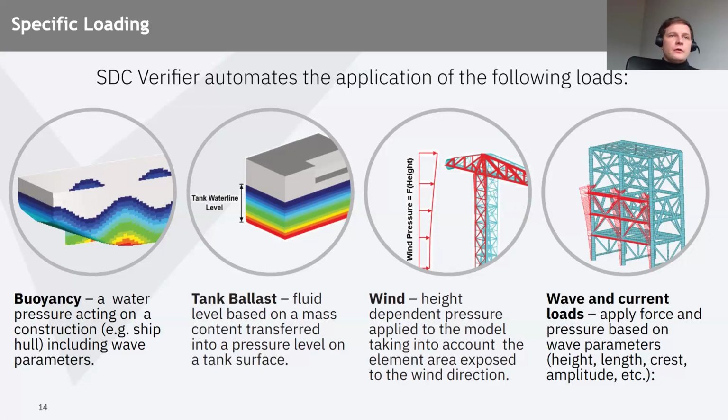buoyancy load of water pressure of the floating constructions, or tank loads, or distributed pressure of winds, waves, and so on. So the complex loads are, of course, automated within certain tools within SDC Verifier, and application of the simple loads like nodal forces, displacements, temperatures, and constraints are done in a single interface in a few clicks.